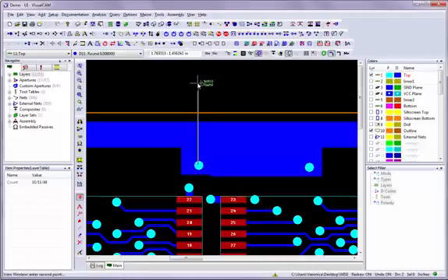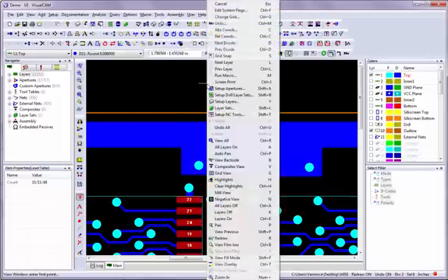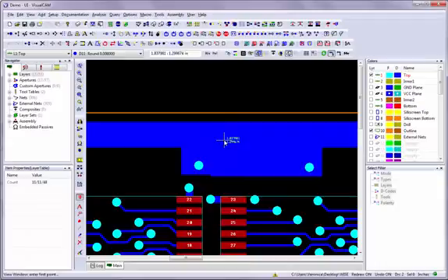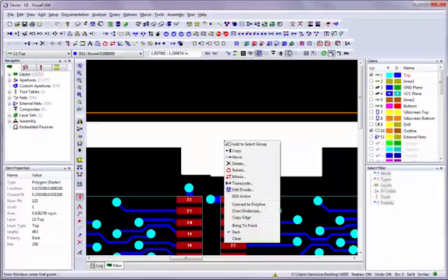There are two default behaviors for the right mouse button depending on where your mouse is pointing when you click it. If the mouse pointer is hovering over a blank area in the workspace, when you right-click, a pop-up menu will appear listing shortcuts to all available commands. If the mouse pointer is hovering over an object in the workspace, that object is selected and a much smaller pop-up menu appears with only the commands that are available for the type of object selected.